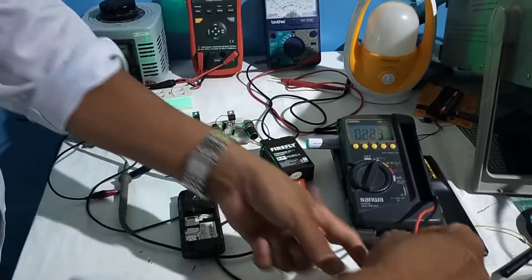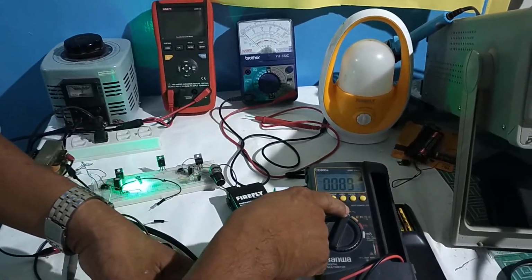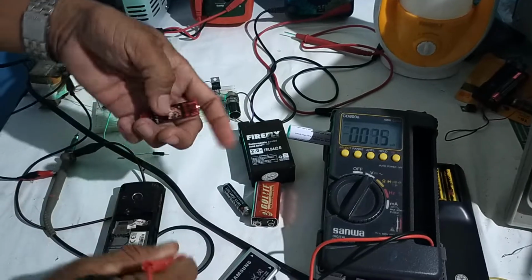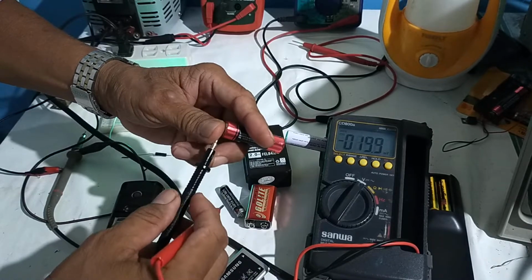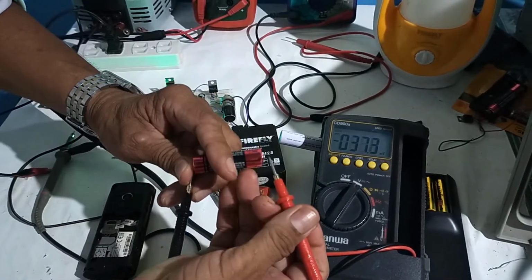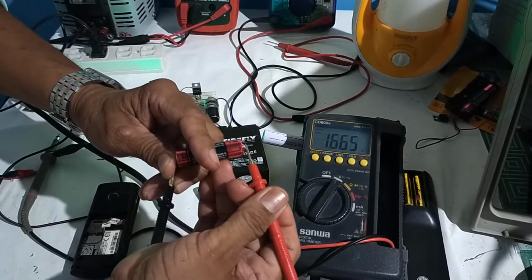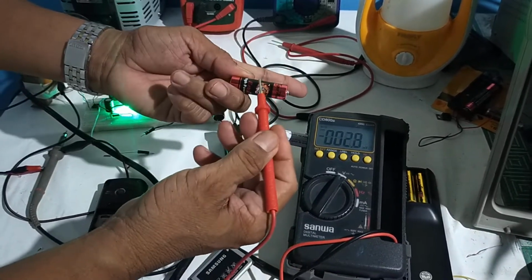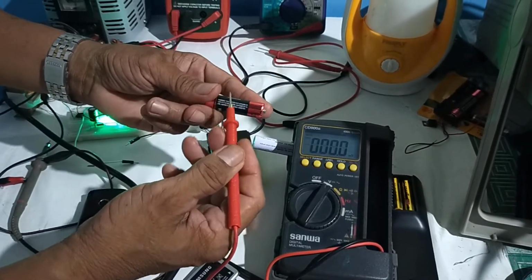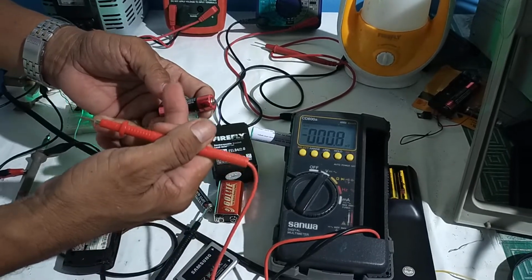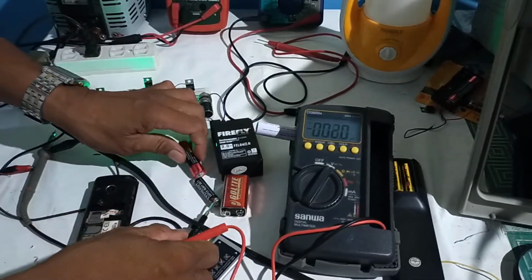Okay, let us measure. We will set this one to voltmeter DC. And let us measure the voltage. Remember that battery is the source of the DC voltage that has fixed polarity. We have here the positive side. It is 1.6 volts. And it is labeled here on the surface of this battery, 1.5 volts. But since this battery is still new, we can measure 1.6 volts.